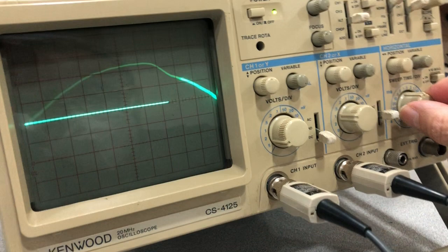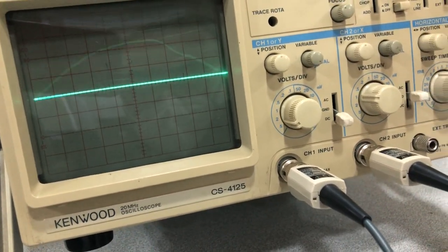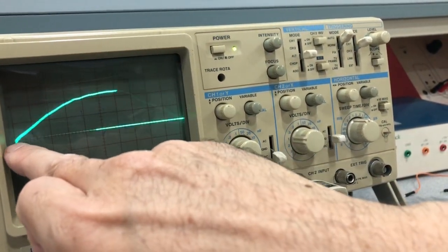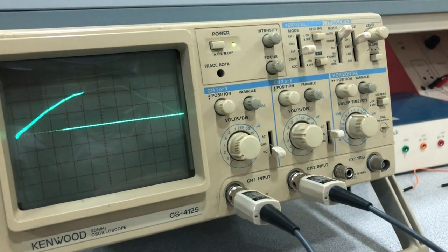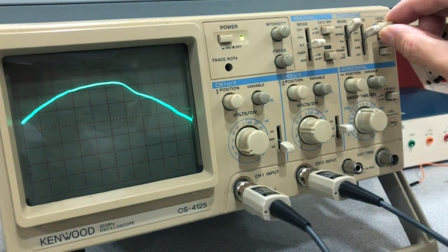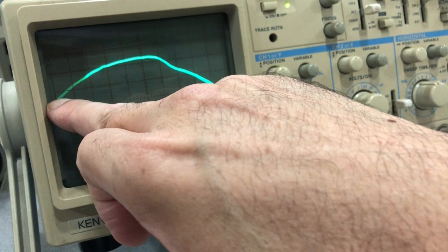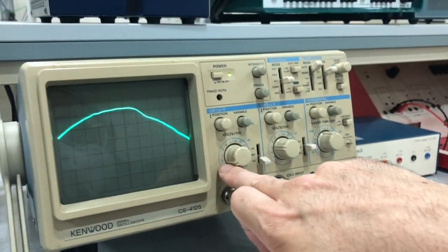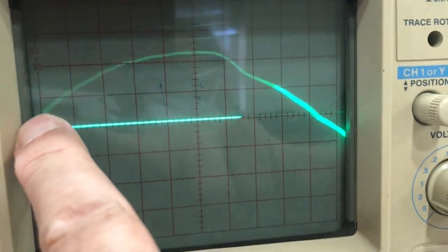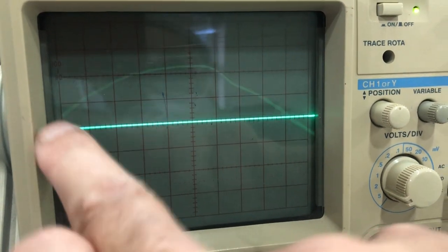The first half cycle is not starting exactly at zero, but it's acceptable. Why? Because I can play with the level knob. I can modify it to cross this signal exactly at 0, so the sinusoid starts plotting at 0, but when I raise it up, it's going to delay. I have a horizontal line that I raised, and it's making intersection at 2.5 volts now, because I have 5 volt per division. So that's why the sinusoid is not starting plotting at 0, because I raised my triggering level line to 2.5, and the intersection happened at 2.5.